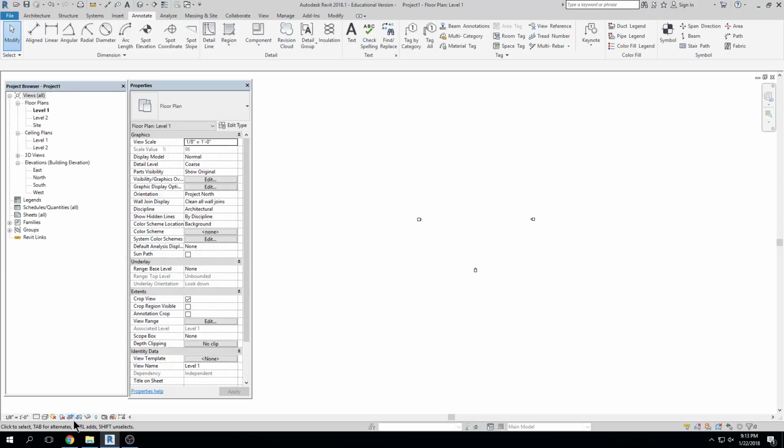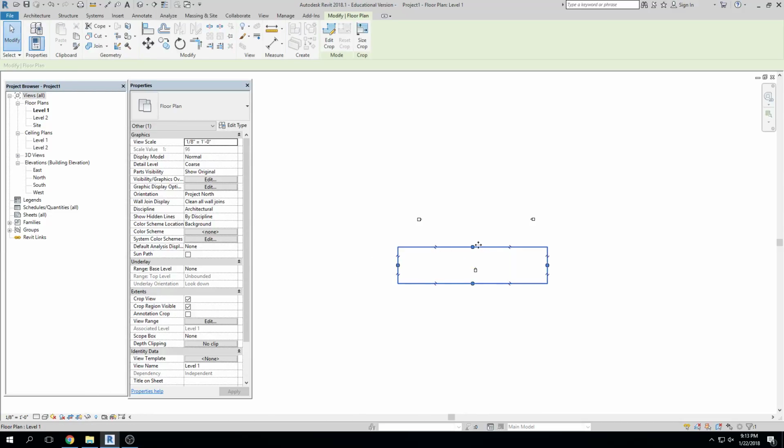But I just want you to remember that down here at the bottom we have Show Crop Region, which turns it on so it's visible, and then we have the ability to make it larger or smaller to show things, okay? I think the last time I presented this assignment, I tricked everybody and cropped it all out and turned it off. Yeah, that's true. There you go. A little bit. I thought I was acting a little bit like Jeff Plant, actually. Anyway, you're right. The crop region will affect things when you mirror it. You have to think about that because it will cut it off and you'll think, where did it go? It's the crop region.